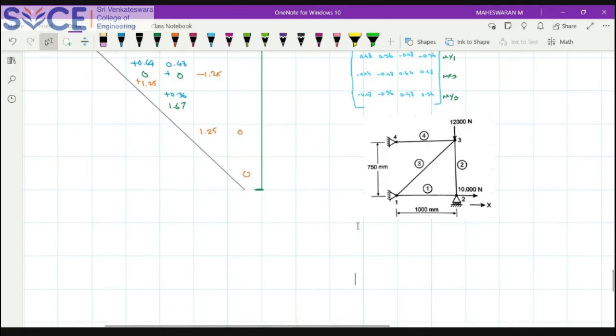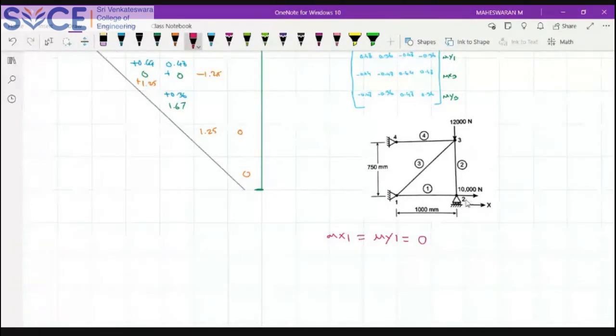For that, let us identify what my boundary conditions are here. If I look at this boundary condition, you can see that nodal point 1 is fixed. So ux1 and uy1 are both zero, which means it is fully fixed. So I no need to look at ux1, uy1, and I can eliminate these columns. Next, similarly, nodal point 2 has a roller support. It means that ux is free, but y is fixed. So uy2 is fixed here, that is 0.